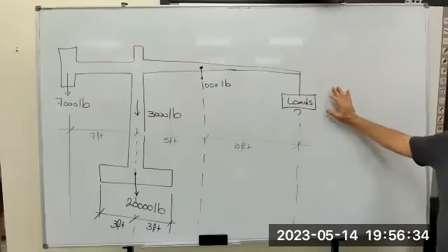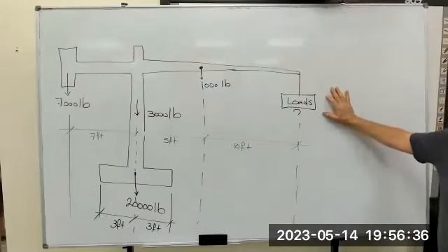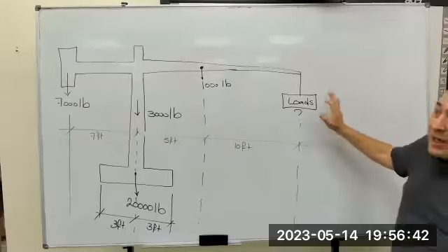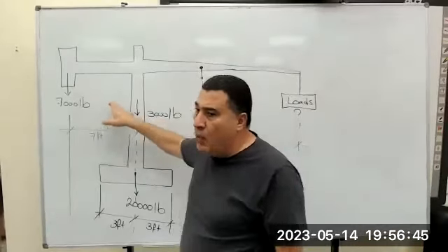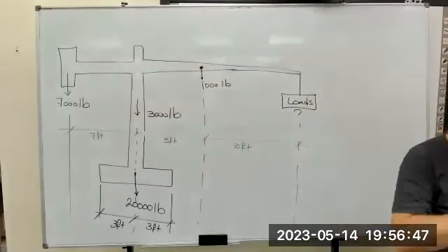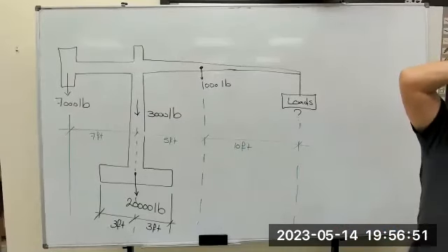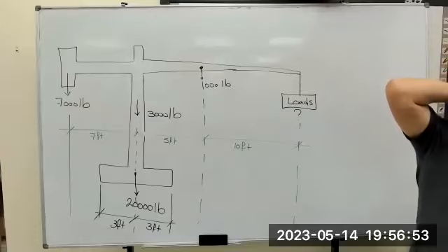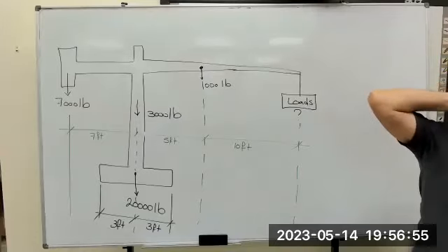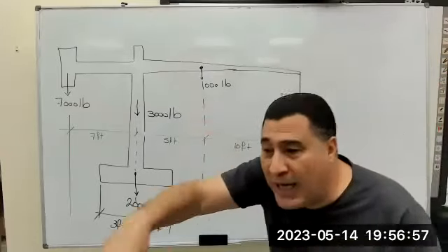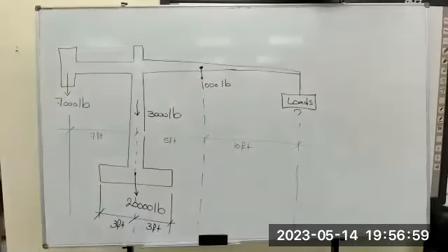Assume the design load is X, due to the counterweight and boom length, the maximum load we can carry is X, in kips, tons, or kilonewtons, whatever the unit. Assume you carry a load of 3X. What will happen? 100% the system overturns.